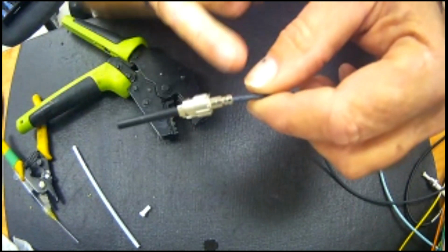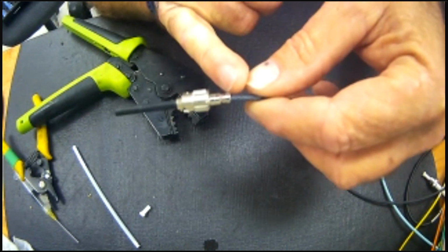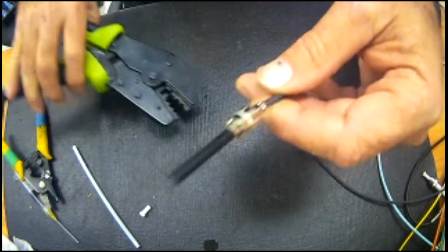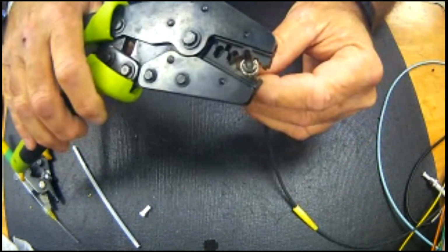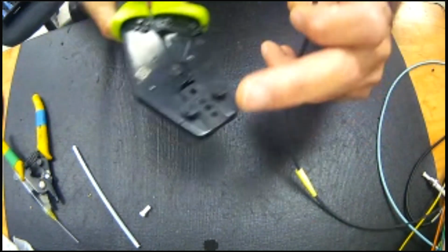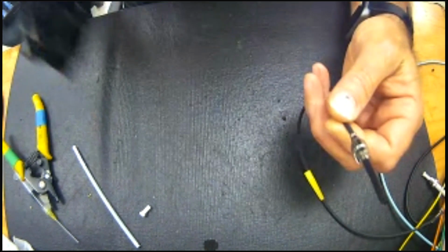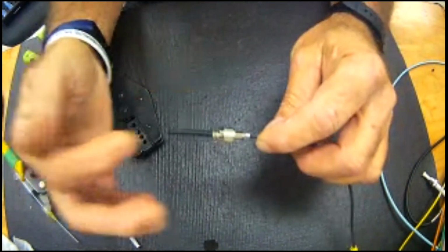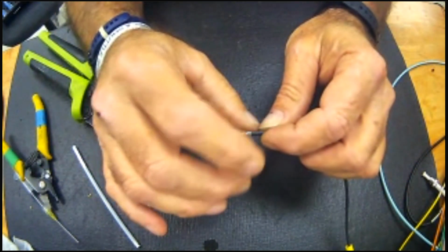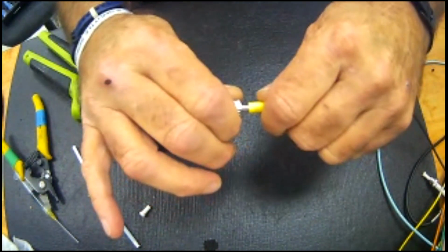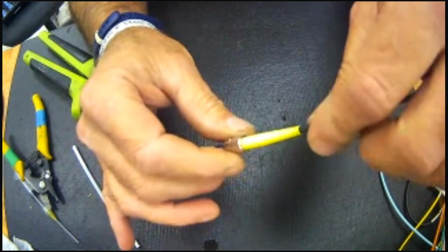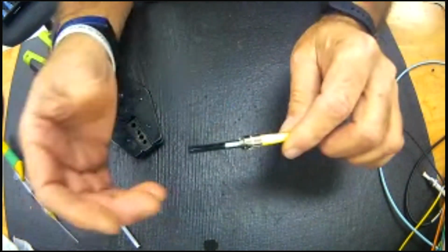Now this is a stepped ferrule. In the back of it's going to grab the jacket. In that case, it's 151, which is not common to the RF world or to the coax world. But like I said, it's an inexpensive die and an inexpensive crimp tool. So 2 steps. We've grabbed the yarn. We've grabbed the jacket. Now we're going to slide the boot up. It goes snap. It actually pushes the excess of yarn that you saw out of the way.